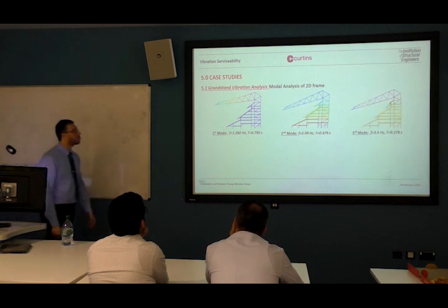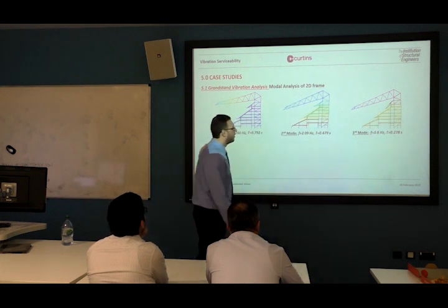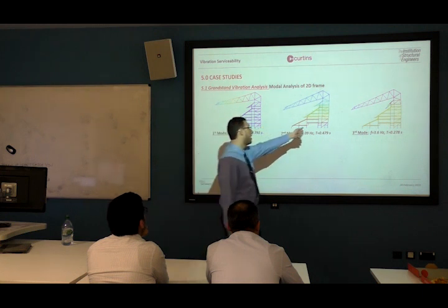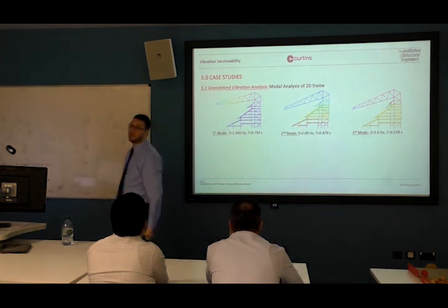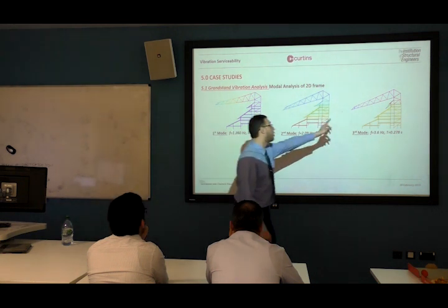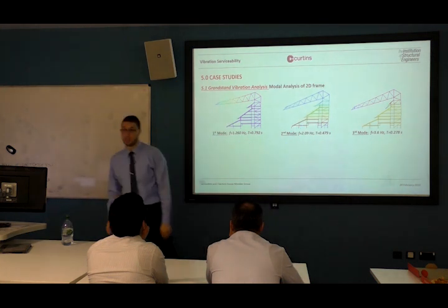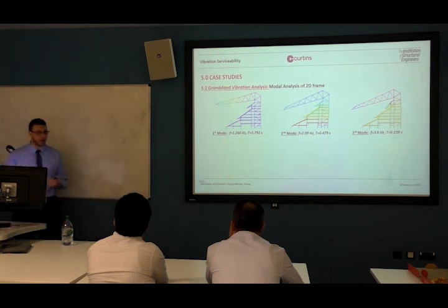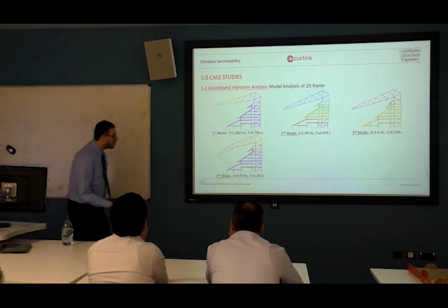Now, the third mode was vibration of the top raker here. Can we excite it if we are sitting? Yeah, of course we can. If we are sitting here and jumping, and someone is playing very exciting music, we can create this mode shape. The frequency here is 3.6, which is less than 6 Hz. So we have to think about a time-domain analysis, and check other modes as well, up to 6 Hz.